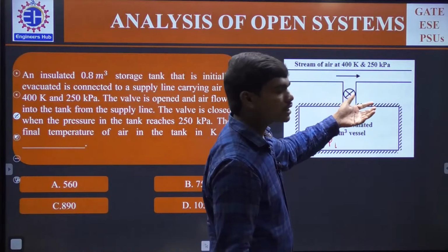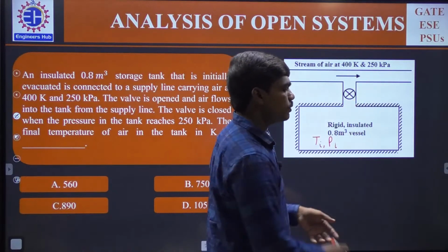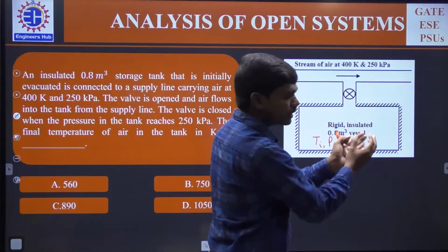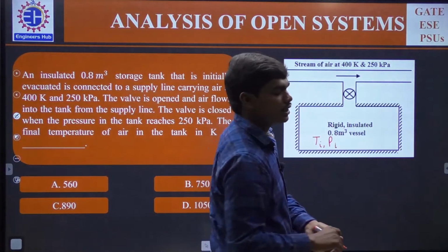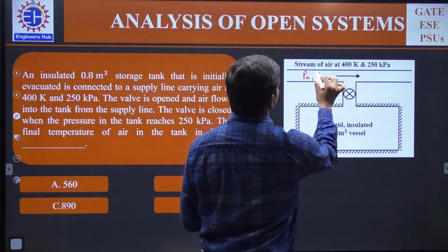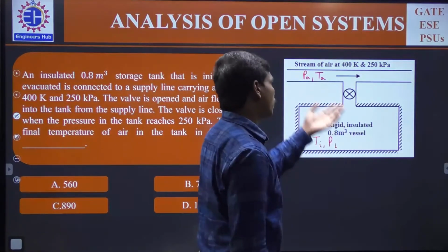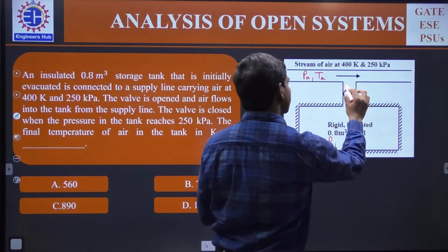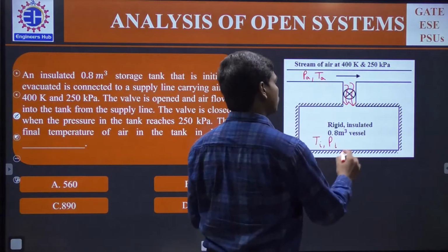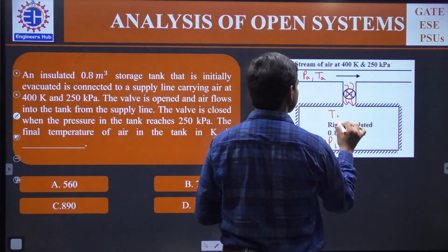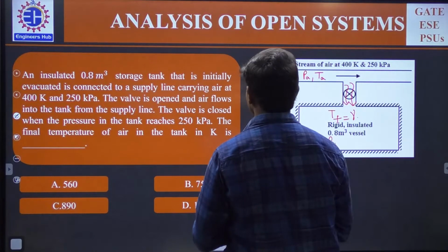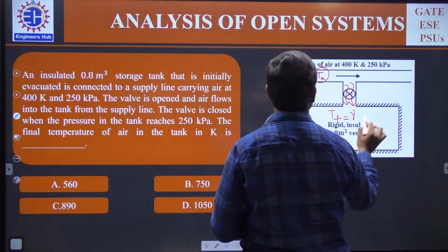Generally you take this for filling gas cylinders, because there is a pipeline which carries the fluid inside it, and you will be taking stock of some fluid in a container like our gas cylinders. Okay, so Ti, Pi, and let us suppose this is Pa and Ta in general. Once some gas starts coming in, the final temperature will be gamma times this pipeline temperature.